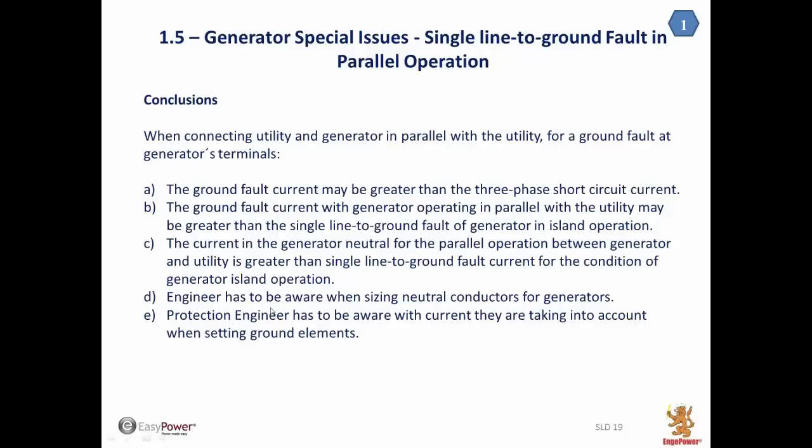This is very important also for the power system analysis engineer. The engineer has to be aware when sizing neutral conductors for generators. And the protection engineer has to be aware of the current they are taking into account when setting the grounding relays, because if your relay is in the generator neutral, your relay will see this big value of short circuit current.